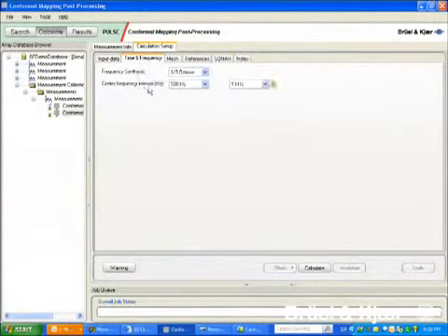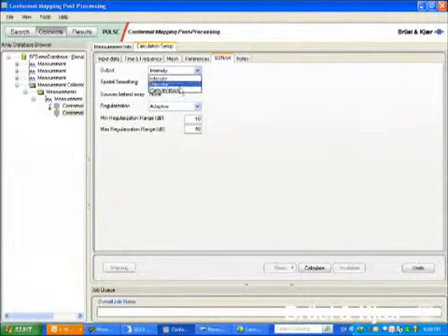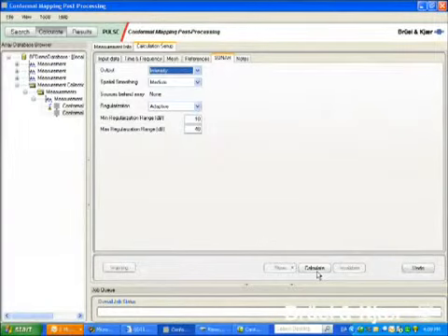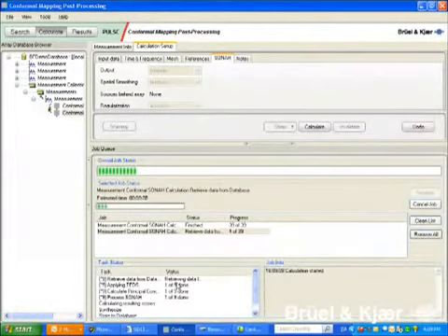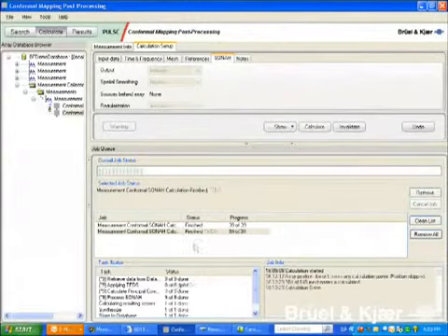The frequency analysis may be either 1/3 octaves or narrow band. In the sonar setup, we may choose the result function: sound intensity, sound pressure, or particle velocity. For source identification, we'll normally choose intensity. Typical calculations last a few minutes, and when they have finished, we can switch to the results window.